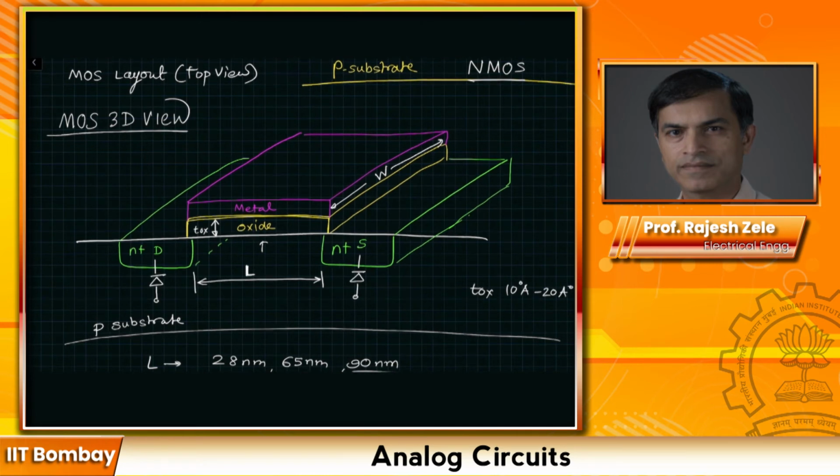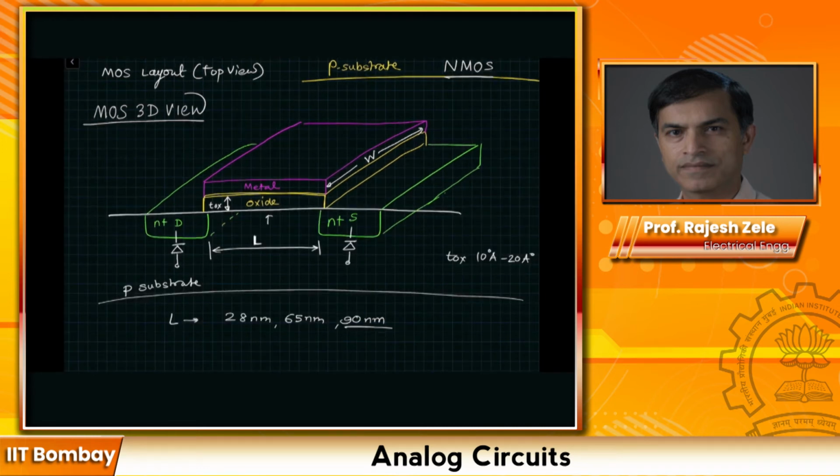As more and more research was carried out, they figured out a way to deposit silicon itself. Instead of metal, we would use polysilicon. Polysilicon is a semiconductor by itself, but you can dope it heavily and it will start acting like a metal. So this had 3 advantages. One is the polysilicon is used to align the source and drain region. Let me explain what that means.